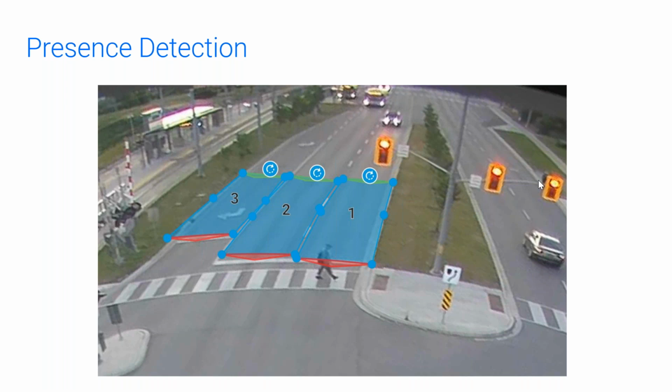So the more cars that are coming, the longer the phase holds, and then eventually it'll gap out because the time between detector hits becomes too large. So understanding how you want your intersection to operate, and how you want the phasing to accept the detectors, are all a foundational layer of designing it in the TrafficLink portal properly.